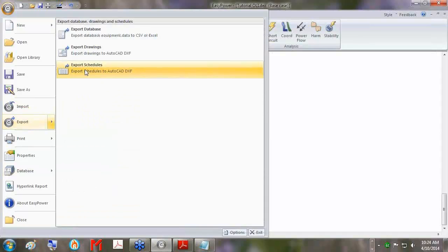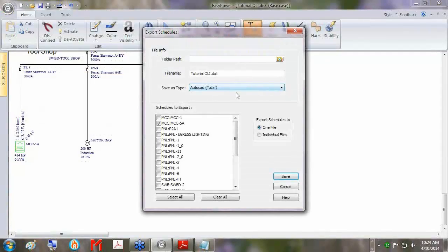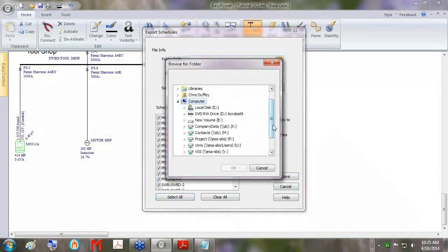There also is this ability, you can export your schedules. Generally this is for say DXF files, primarily AutoCAD. You can also export these as XML files here, which you end up opening with Excel, and then you can adjust it as you see fit there. So if I was to open up all of these, we'll create our Excel file. Let's save it on the desktop here.